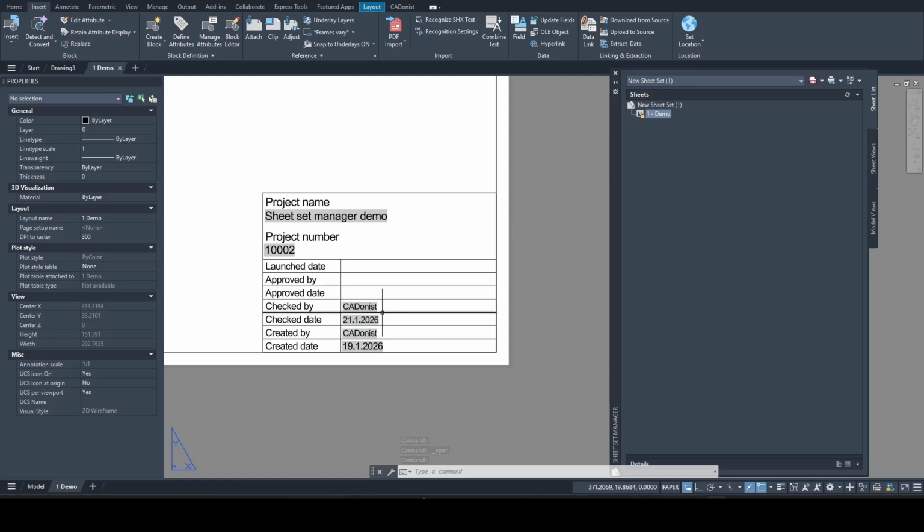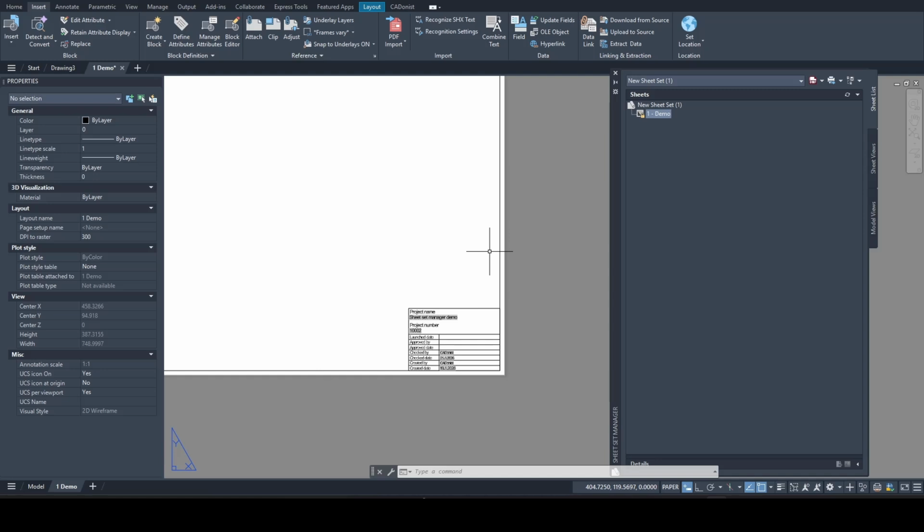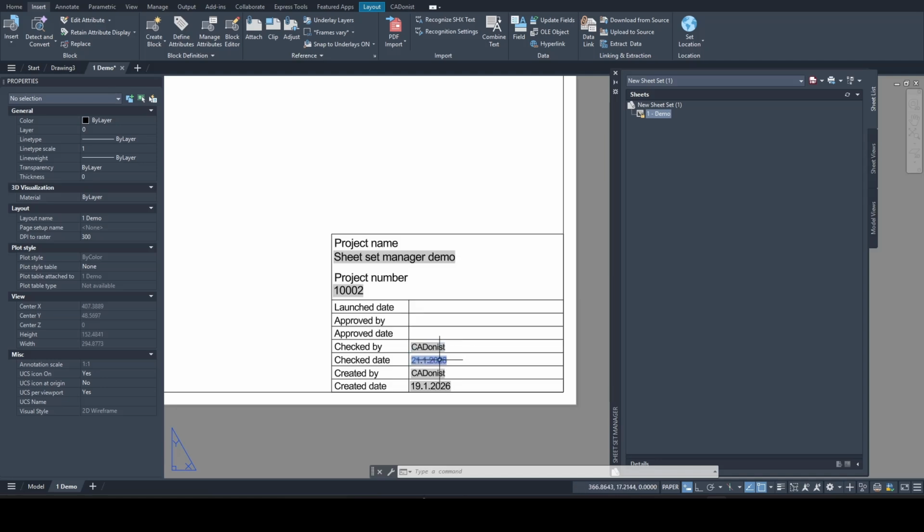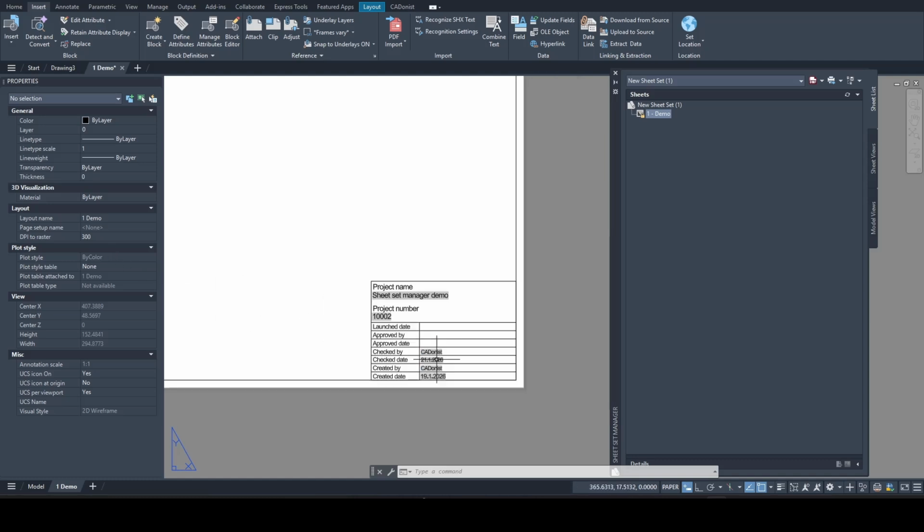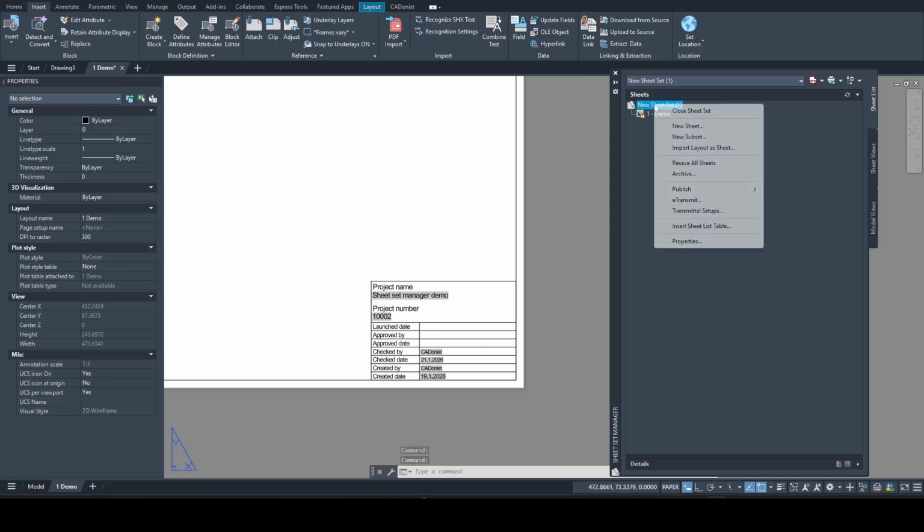Why is that? Because this sheet was created as a copy of the template, at the moment the sheet was created. At that time, the font height of these 3 elements was 2.2 mm, and that exact state was transferred to the sheet. Any new sheet you create afterward will use the updated template.